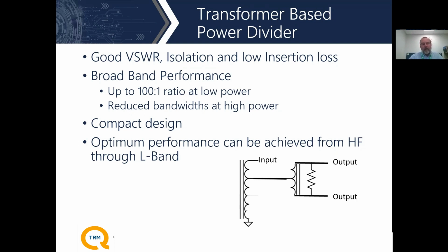It's a compact design, especially if you're dealing with frequencies at HF, VHF, UHF, right through L-band. This sort of technology works very well for lower frequency work. And really the upper end of this is about 2 gigahertz, being practical about how far this technology actually operates. Like I said, it is an excellent configuration for lower frequency projects. Again, very broad bandwidth, very good RF performance, but the limit here is the high frequency. These circuits do not work very well above 2 gigahertz.